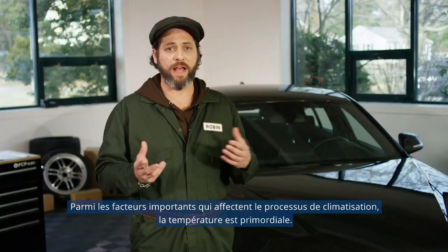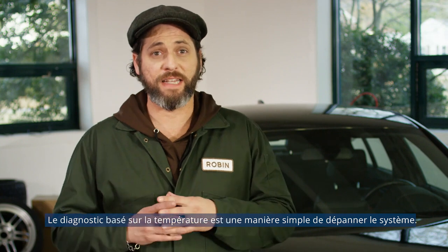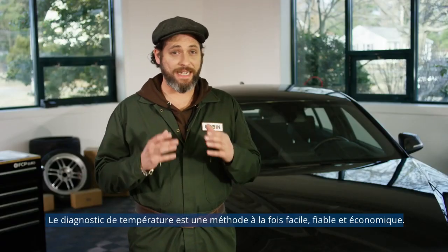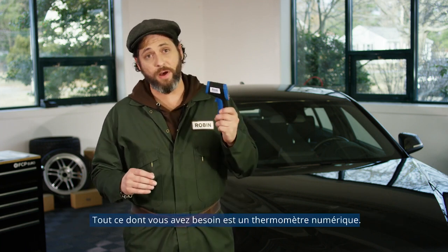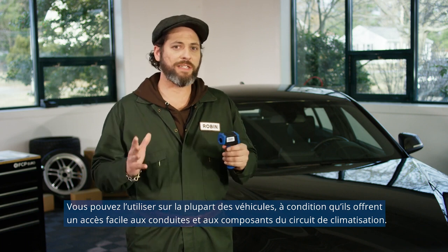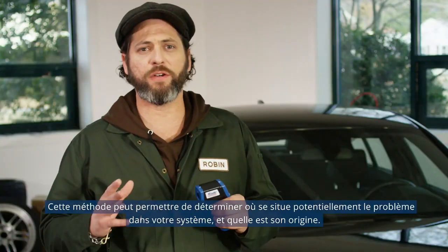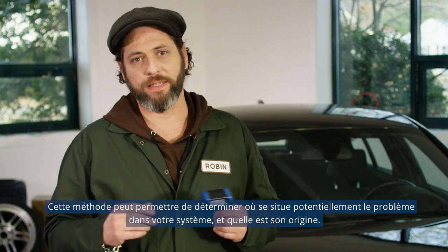Out of all the important factors that determine the AC process, the temperature is key. And here's why. Temperature-based diagnostics is an easy method to troubleshoot the system. All you do is simply measure the temperature at different places in the loop. That's it. It's that simple. The temperature diagnostics method is easy, reliable, and cost-effective. Everyone can use it. All you need is a digital thermometer. And it works on most vehicles as long as the vehicle has unconstrained access to the AC loops, channels, and components. This method can tell you where the problem in your system is potentially located and what the problem basically is.